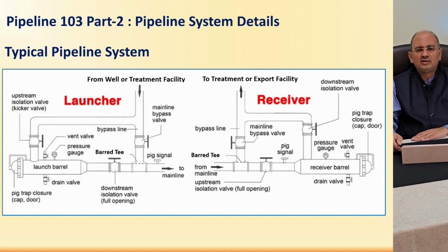And at these low points, the stagnation of the liquid or water can happen, and then this can start a corrosion reaction at the 6 o'clock position in the pipeline. So to overcome that, the pipeline requires some kind of measures like chemical inhibition, which should form a film inside the pipe, which will avoid or minimize the start of corrosion at such critical locations in the pipeline.